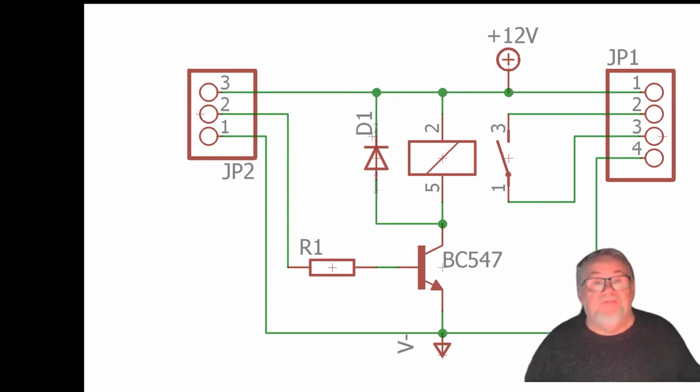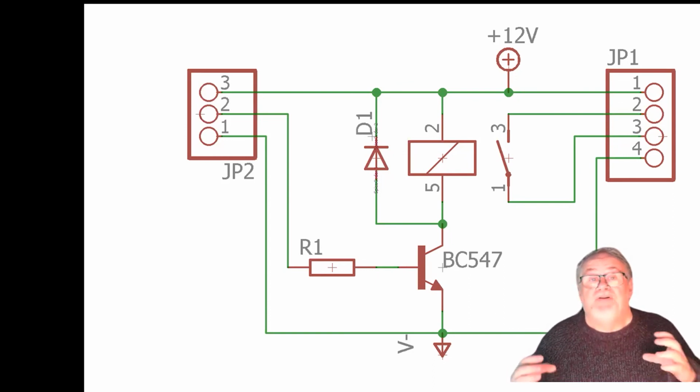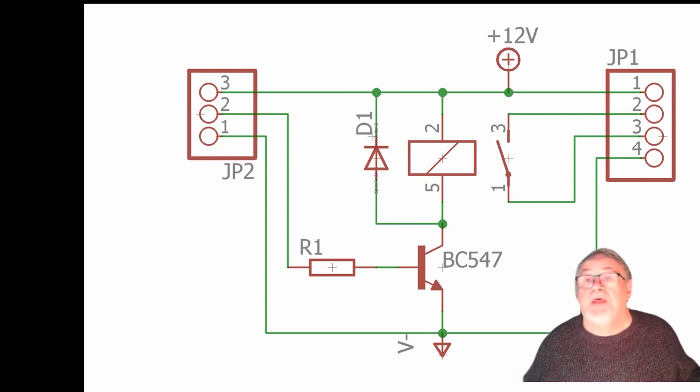The capacitive trick worked initially, but people found that if you put a capacitor across a coil of wire, you sometimes get a resonance, and it caused as much noise as it was saving. And sometimes the spark itself was turning into the coil of wire, and the capacitor was turning into a wee transmitter, and you were getting electrical noise, which was causing more problems than it was saving.